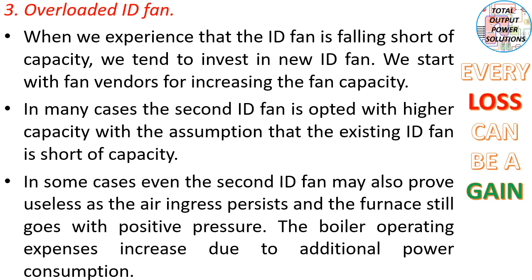Then, overloading of the ID fan. When we experience that the ID fan is falling short of capacity, we tend to invest in a new ID fan. We approach the fan vendors for increasing the fan capacity. In many cases, a second ID fan of higher capacity is opted for, with the assumption that the existing ID fan is short of capacity. In some cases, even the second ID fan may prove useless as the air ingress persists and the furnace still runs with positive pressure. The boiler operating expenses increase due to additional power consumption.